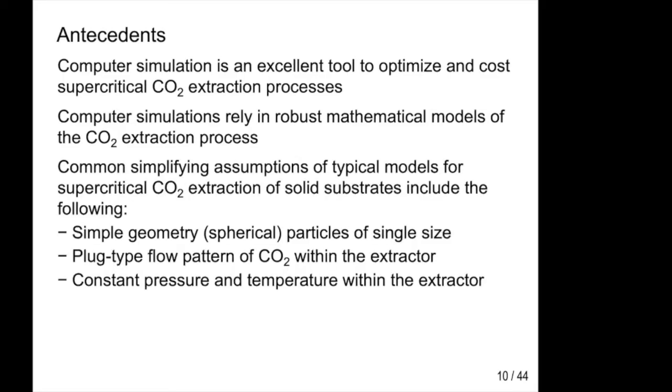Typical models for supercritical CO2 extraction of solid substrate in the literature adopt the following simplifying assumptions: equal size particles of single geometry, spherical; plug type flow pattern of CO2 within the structure; and constant pressure and temperature within the structure.